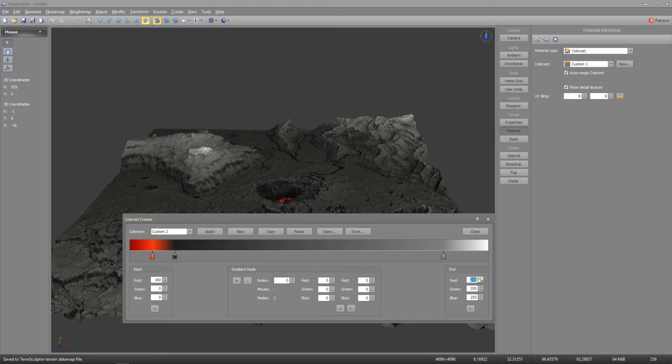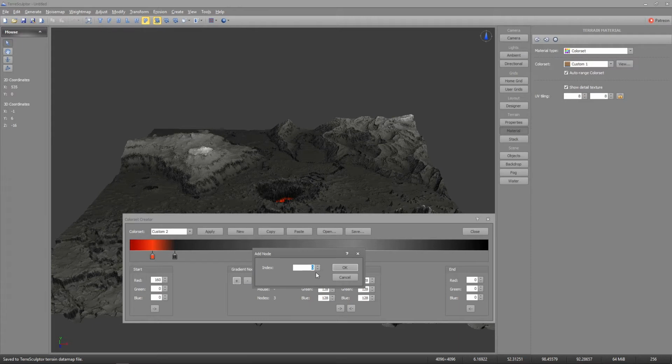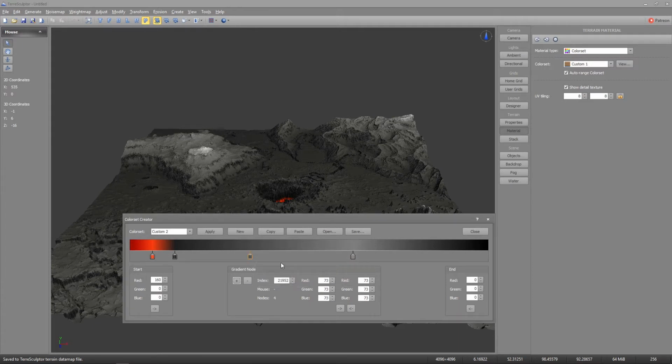The color values on the right correspond to the top of the map, and what's on the left to the bottom. You can move the sliders around to change where the gradient's at. Add new gradients at their index number, which is displayed next to the mouse, or you can double click in the slider area to add one. Here's a box where you change the endpoint of the middle of the gradient. You copy either the left or right side of the midpoint over with those 2 buttons.